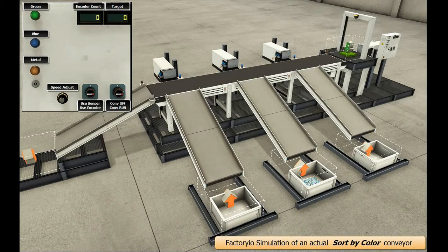In this mode, once the part color is determined, the target position is displayed and the PLC uses this value as the stop point. Now, because of some delays in the system, the belt could actually stop a bit after the set point, so I've created a stop window of basically the set point plus or minus 2. I think this is a good representation of our lab conveyor, with the added bonus now of being able to add and experiment with part present sensors.